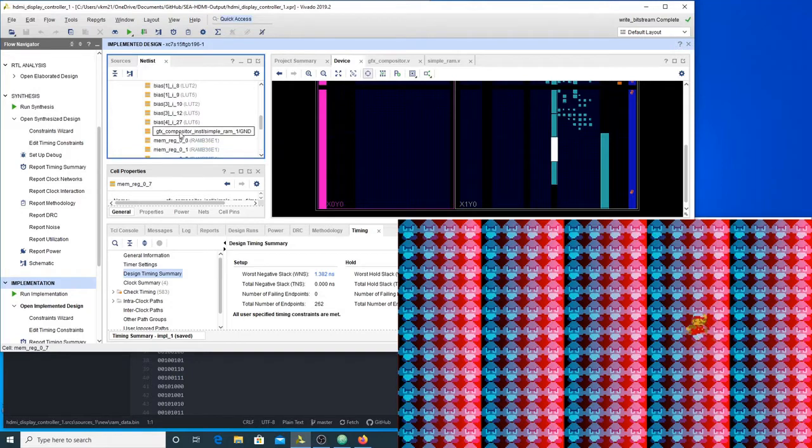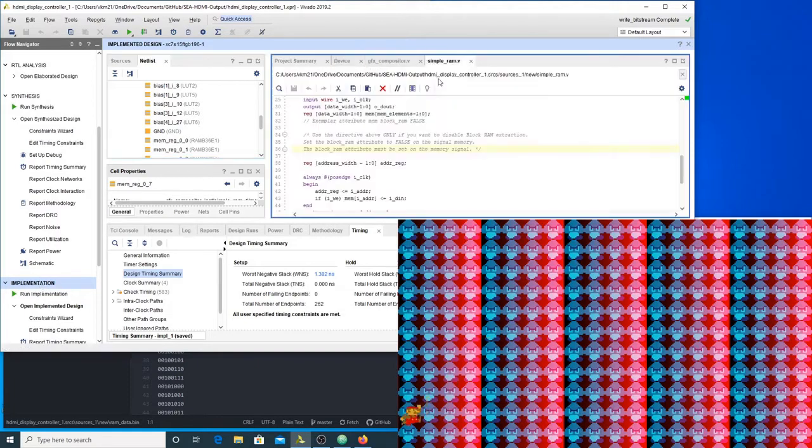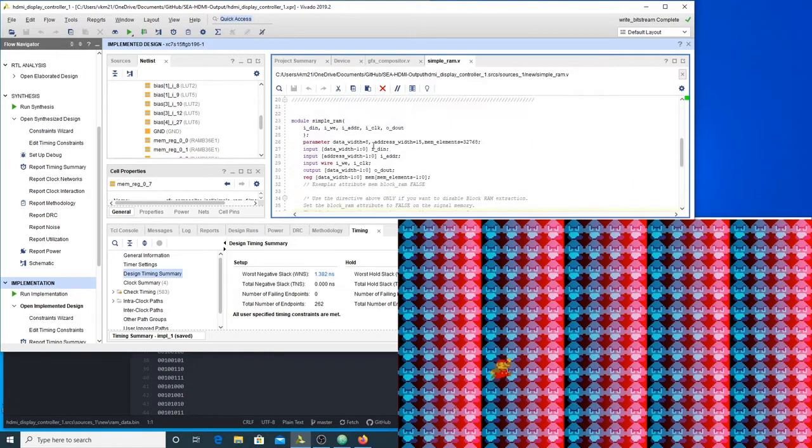So anyway, what's nice about that is, again, super flexible. We can make it do whatever we want within some limits. So for example, over here, I've set it up to be a 15-bit address bus, storing a total of 32,768 bytes. So we're actually addressing individual bytes in memory. It's not a 32-bit thing. It's not a 64-bit thing. I wanted 8-bit, and maybe later we can make it more capable.